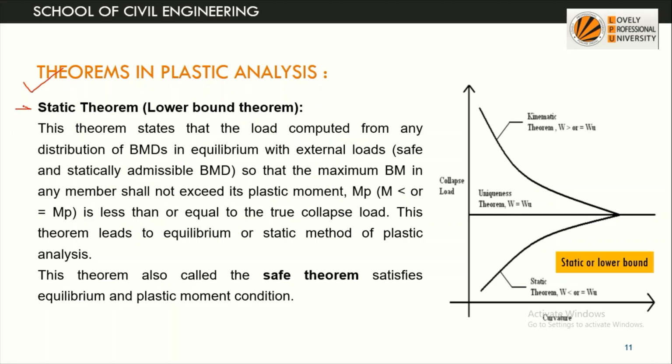The first theorem is the static theorem or the lower bound theorem. This theorem states that when the load is computed from any distribution of bending moment diagram in equilibrium with the external load, meaning the structure is still under equilibrium, there is no motion with the external load, which is safe and a statically admissible bending moment diagram, so that the maximum bending moment in any member shall not exceed the plastic moment.